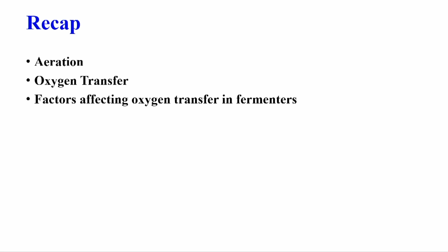So, if you remember, in the last lecture we discussed aeration and what are the different steps involved, particularly in the transfer of oxygen from the air bubble to the cell. We discussed there are 8 steps. However, the liquid film was found to impose the major mass transfer resistance, and further we discussed what are the different factors which affect the oxygen transfer.